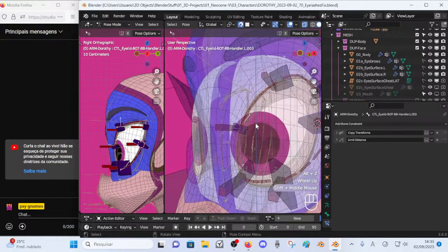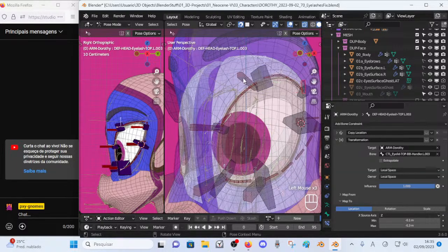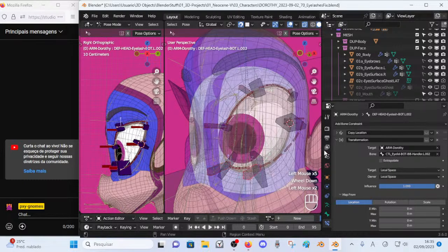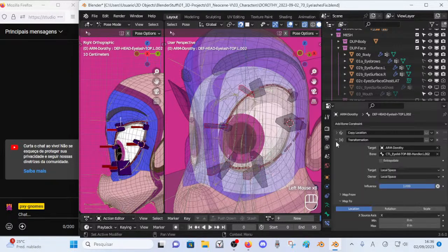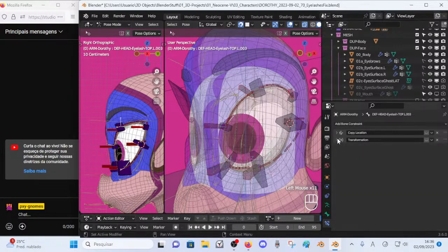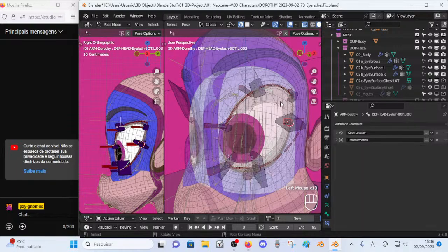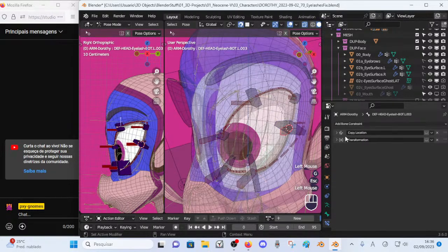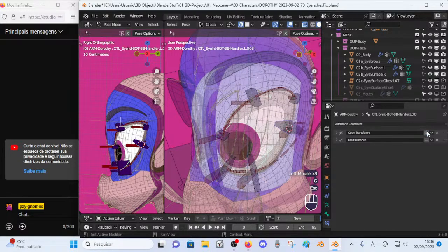But for the other things, we can start with the transformation bone constraint. All right, so the eyelash bones, they have this combo. I have shown it many times already. A copy location towards the eyelid, so currently it's not following, but if we add it, there we go, now it starts to follow this.